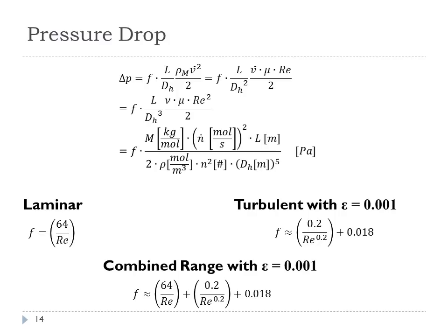And the same is true for the hydraulic diameter. You can see here it goes inversely as the -5 power. So once again, there's going to be some kind of optimal hydraulic diameter to these tubes. And that's what we'll get into later in this course, is how do we actually solve for what that optimal number of tubes is and diameter of the tubes.